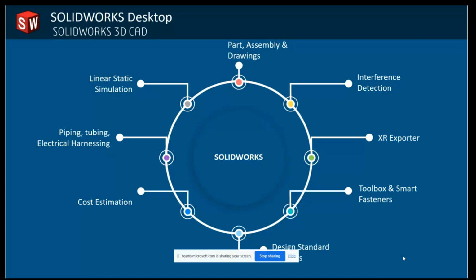Now SolidWorks also has a CAD library which includes standard components like nuts, bolts, bearings, washers, etc. We call it the toolbox, which provides easy access for locating, downloading, saving and sharing pre-built 3D CAD models and commonly reused CAD data. And we also have the design checker in our 3D CAD itself, where we can create design standards and check designs or models to create uniform designs and documentation. It establishes design standards and then checks the drawings against them as you design to ensure consistent and complete drawing outputs.